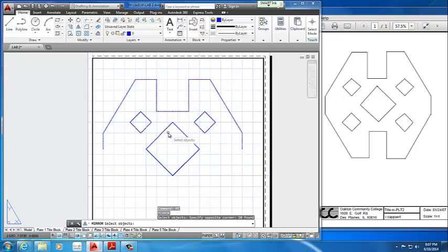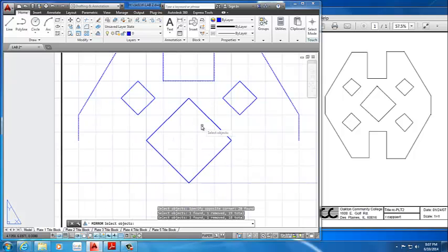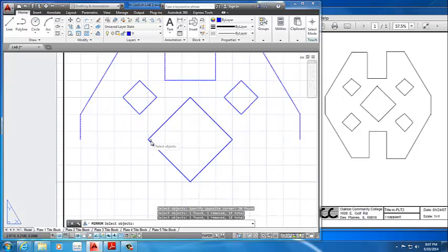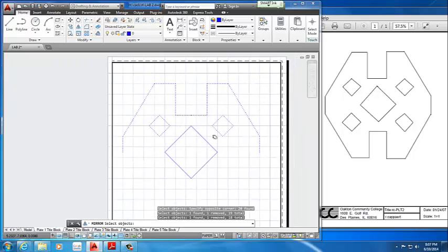To do so, you hold Shift and you click on the lines you want to deselect. So right now I selected everything and I deselected these two tops because I didn't want them to be mirrored. And you can tell what has been selected by the dashes. And it's going to ask you to select objects. No, I'm done for now. 18 total. That's right, because I had 9 in the beginning times 2, 18. So I'm just going to click enter or space.